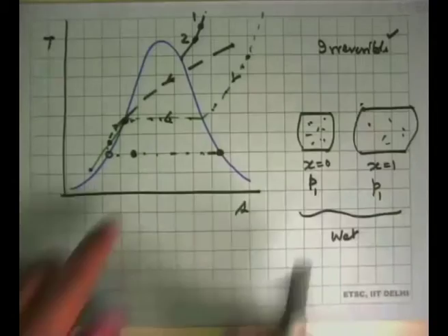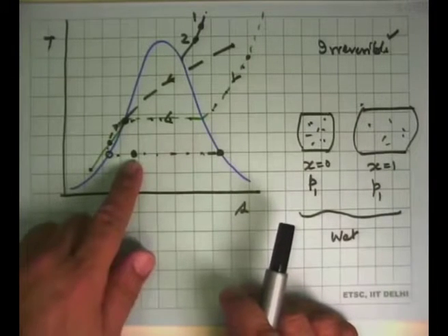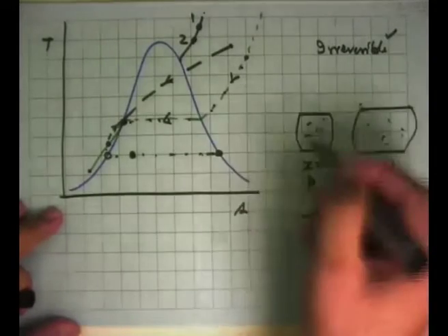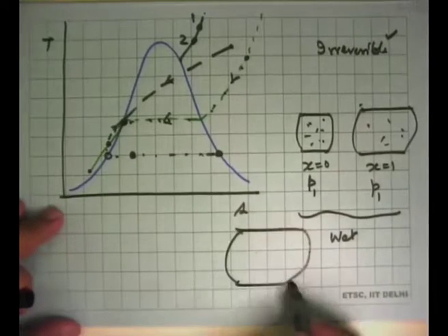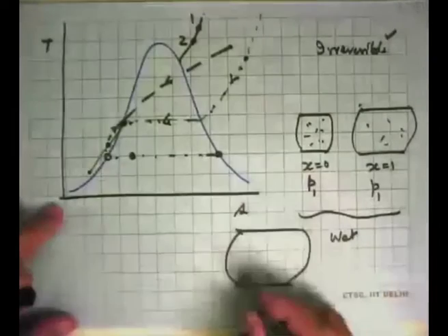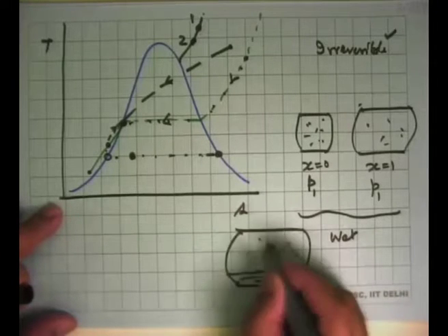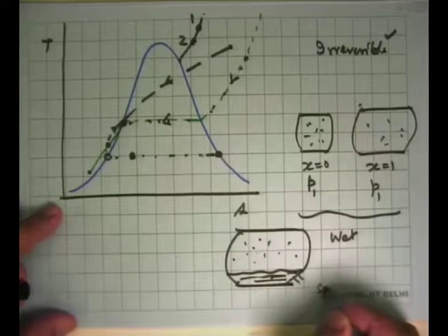So the question is, is this also reversible or irreversible? And one can argue that, look, if you took all this mixture and put it in another vessel and allowed it to just stand there, we know that by gravity the liquid water will come down here, the vapor will stay up there, and if we take this out, we get our saturated liquid.